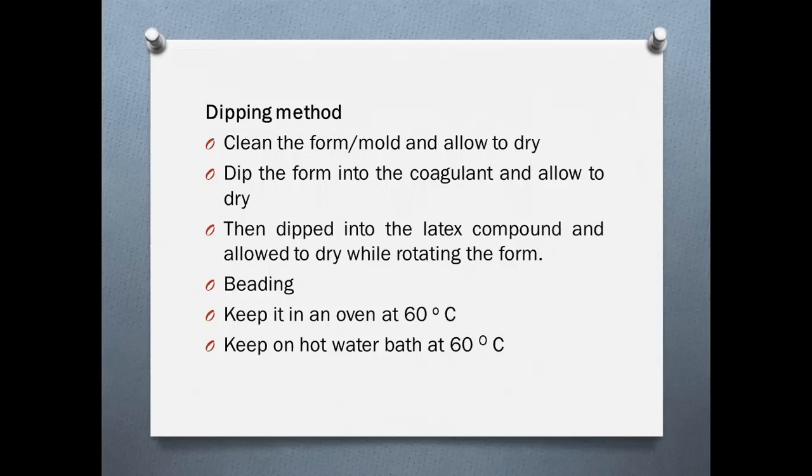The crucial step is latex compounding. You have to do it very carefully. And when you are adding these ingredients into the latex, you have to add them in a sequential order.